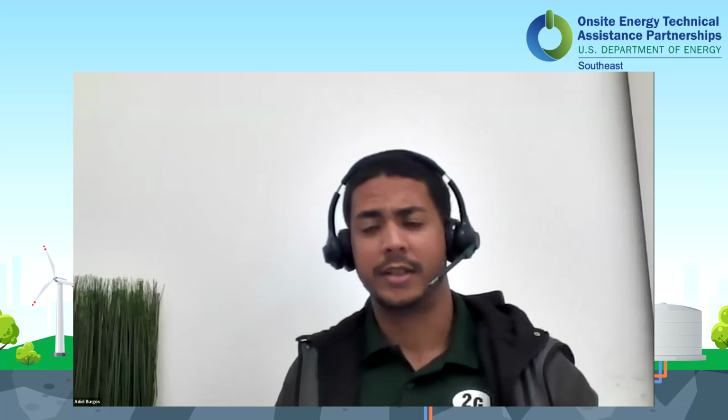I guess I'll go first, and to me, one of the keys to success for projects that go well is planning. I think that planning and making sure to invest the proper time for the design considerations of the installation, like even planning for maintenance, like planning how you're going to take care of the equipment, the location and access.